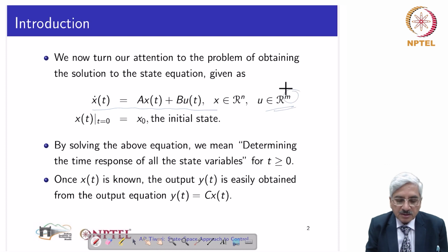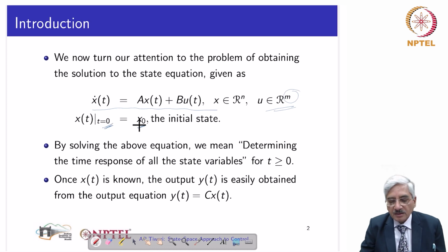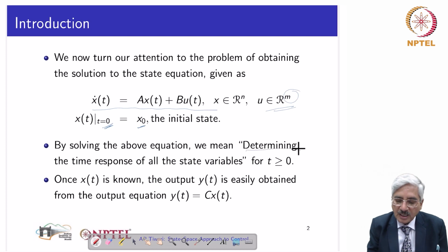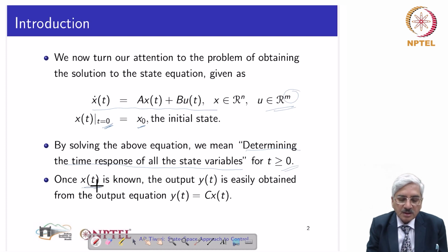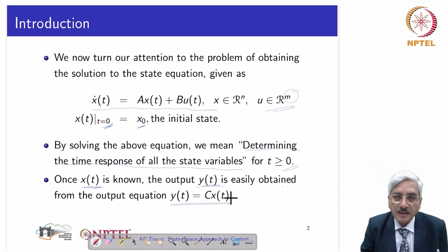Initial state is specified at time t equal to 0 as x0. Now we have to obtain its solution, which means determining the time response of the state variables for time t greater than or equal to 0 given the input. And once the state x(t) is known, then the output is easily obtained through y(t) equal to Cx(t).